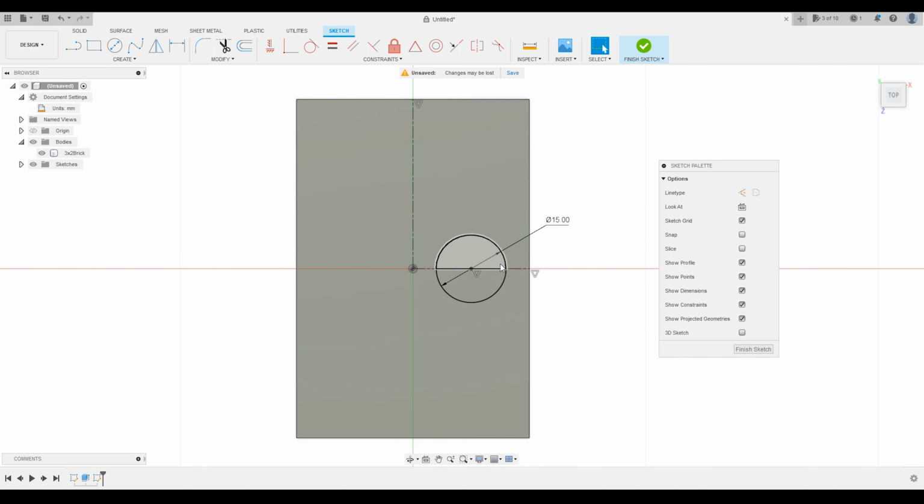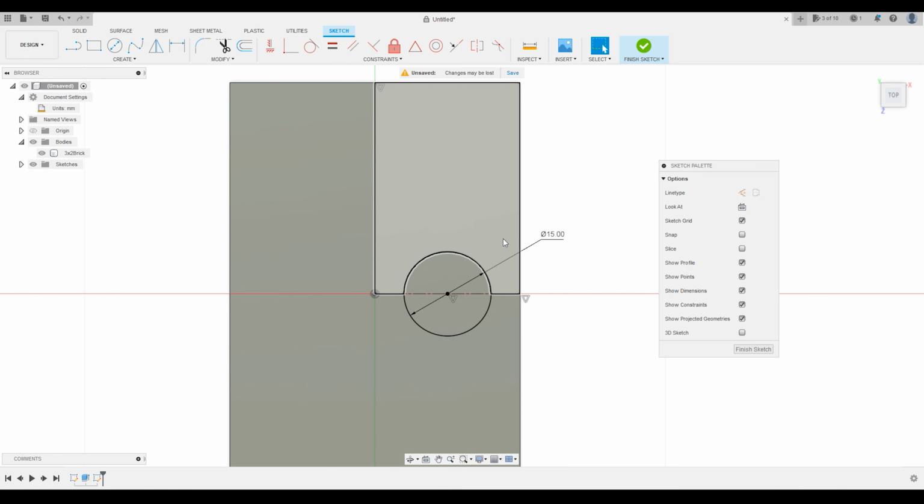All right, now I know geometrically that my next construction brick is going to be centered along this same line. So what I'm going to do is click a line again, click on that midpoint and drag straight up. Actually, I'm going to not drag straight up because I want to show you that if I click here and I hit escape, what I can do is I can add a horizontal or vertical constraint by clicking this line, hit the horizontal or vertical constraint, and as you can see, now it is locked to the vertical.